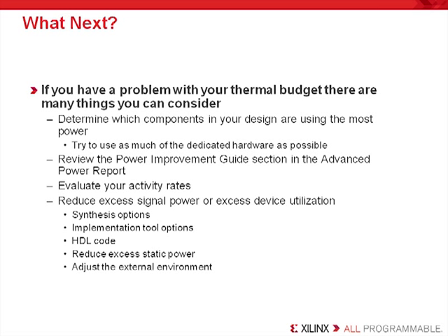You should also evaluate the use of the implementation tools. Enable the implementation tool settings which will favor power optimization. Experiment with the map and PAR, that is the place and route options, which may affect power, such as options which modify the input netlist, packing, placement, or routing resources used. Loosen the constraints when possible to get a more tightly packed design.